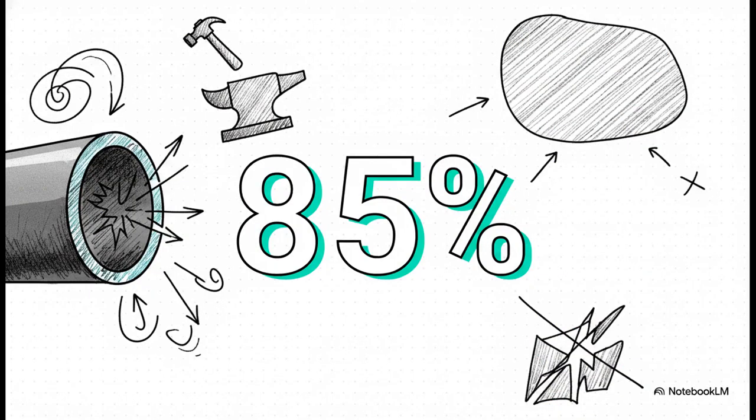And here is the magic number, 85%. According to the standard for CVN impact tests on pipe bodies under 508 millimeters, the average shear fracture area has to be greater than or equal to 85% at the specified test temperature. This is crucial because it ensures the steel behaves in a ductile, forgiving manner. It tears safely rather than just shattering like glass. This metric right here is exactly what stands between a safe, localized pipe failure and a massive infrastructure disaster.